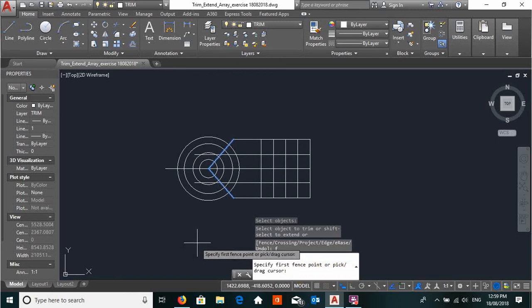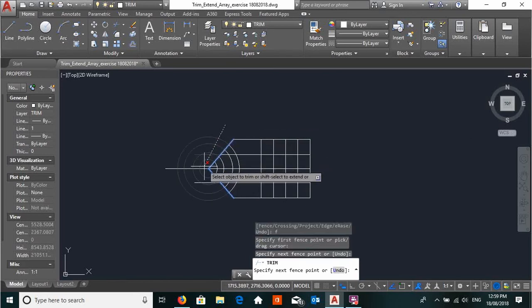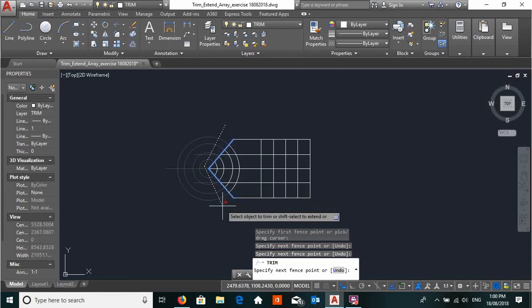So we are going to create a fence line. It's almost like fencing off something. We are going to click in 3 points to create that fence, and that means it's selecting all these lines that are on the left hand side of the pointy edge of the pencil. So I'm going to click up here. So click once, click somewhere in the inner circle, not in here, okay, because then that will also eliminate those arcs of the circle. I'm wanting to click on this side because I'm wanting to eliminate the arcs here. And then I am going to drag it out here.